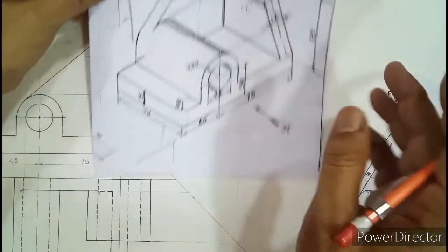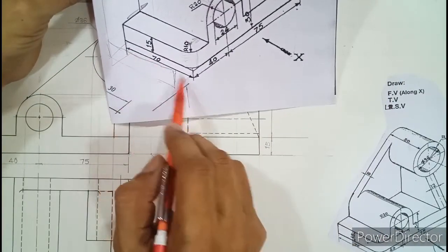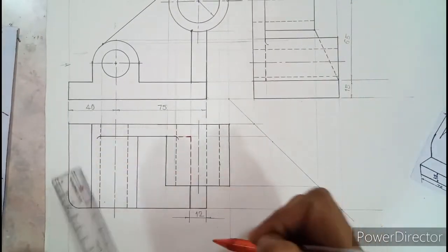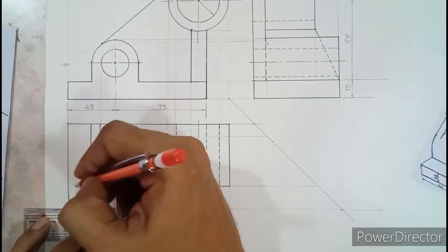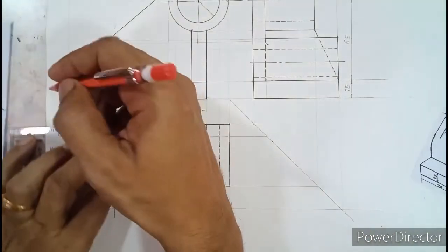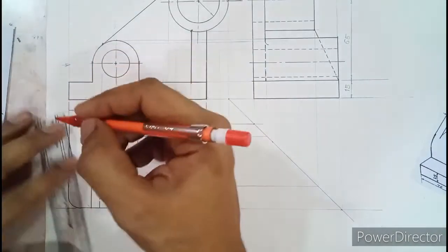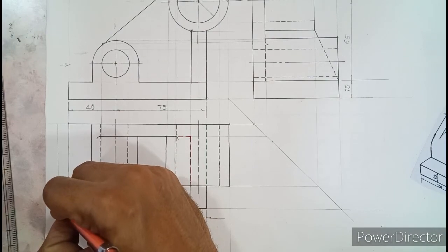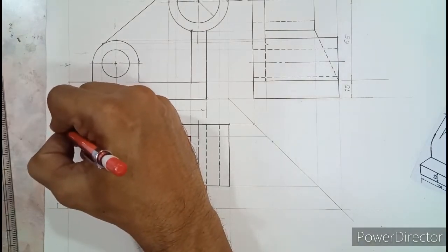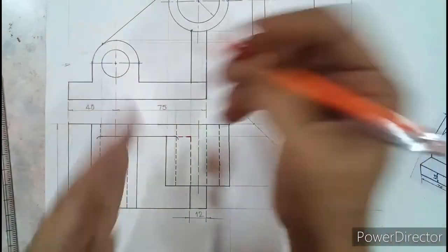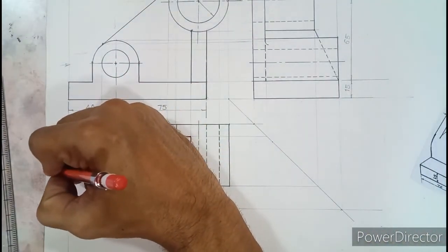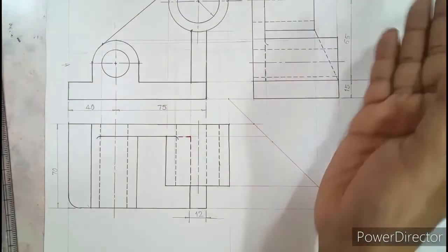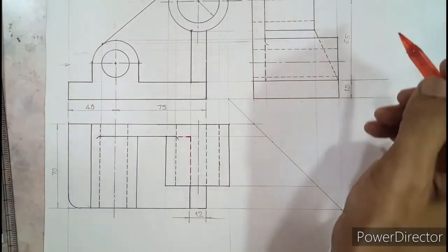Now comes the width of the object. The width of the object is given as 70. Okay, and we can show that 70 in the top view. So this dimension is 70. Top view has only one dimension. So we can extend this here and here, and we can show 70 like this. Always write above the line. So when you just turn over, 70 is written above like this. This is called writing above the line. Look at 70, 65, 15. They are written above as a standard format. Now length, width and height is done.